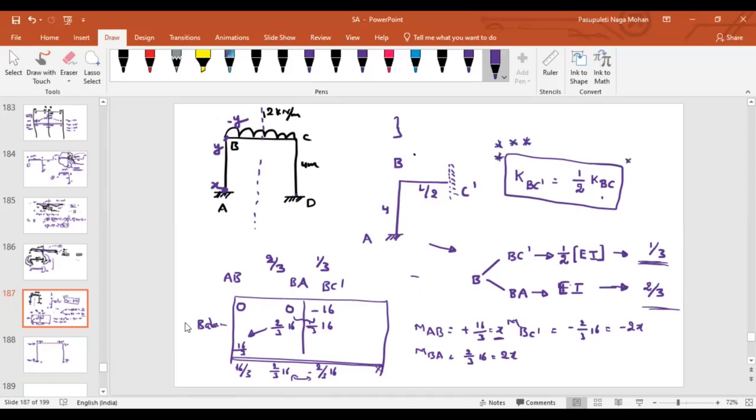If the symmetry of the section is falling exactly at the middle of any beam or column, then we have to consider the new stiffness as half of that value. If it is falling entirely on one of the supports, then we have to consider the entire stiffness. Is it okay?